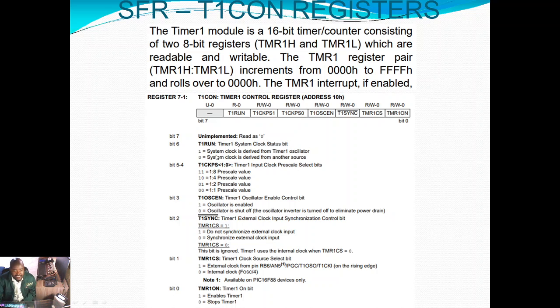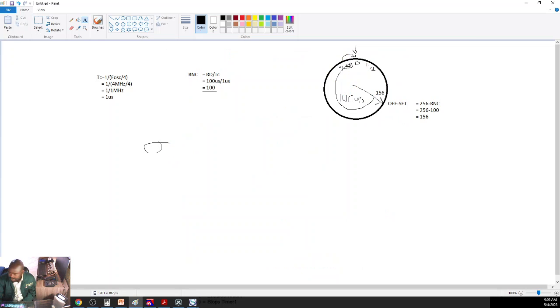It's just an indication of the status of the timer 1 clock. Right, bit 7 is 0. We can get a value here. Now, with that value, when we move it to timer 1, we can configure the rate at which our timer 1 runs, and then we go and set up timer 1 interrupts. Let's start with the calculations. We want to achieve a 1-second interval with our timer 1, knowing that this is a 16-bit timer.